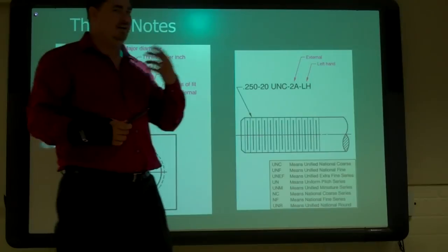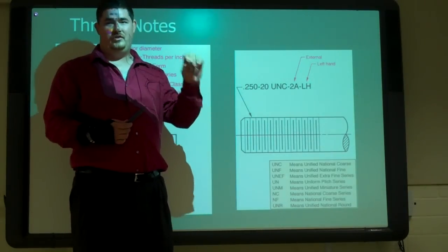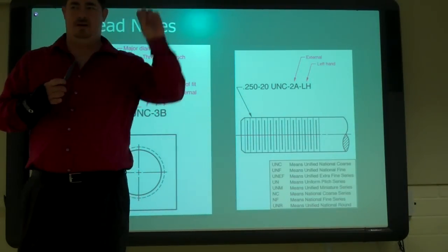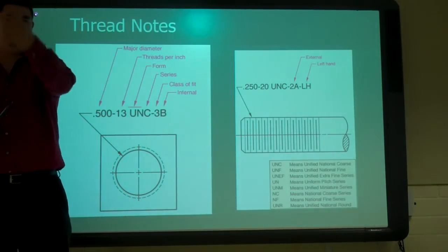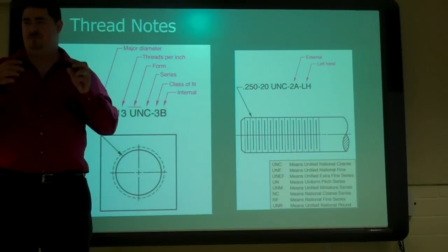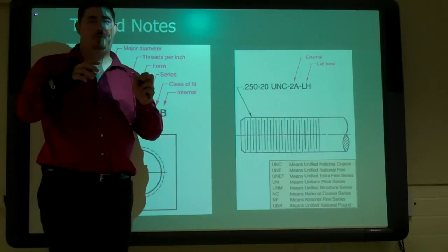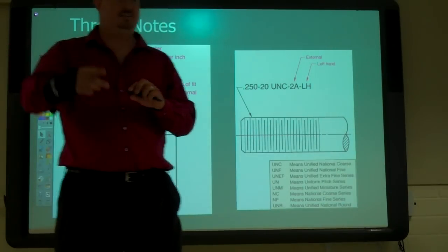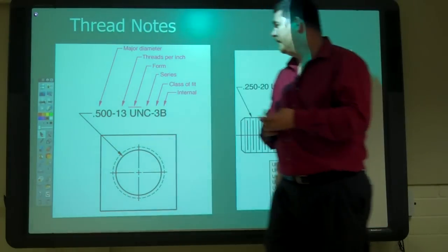They'll also sometimes do that for the lead, or they'll change the pitch on them. So one fitting will be a coarse thread and one fitting will be a fine thread, depending on what you're doing. But with acetylene, they do it left-handed, so there's no possible way that you can even cross-thread it to get onto the oxygen.